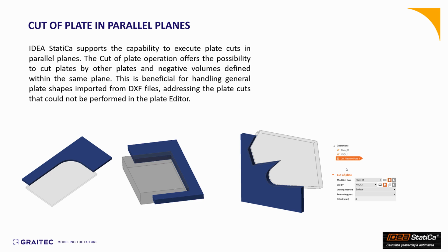Again, this is for cutting of plates. Before, you were able to cut the plates using the editor option or using the negative volume of members, but the problem there was that you were limited to some very simplistic specified sections. For example, you were not able to cut a plate using a DXF import. Now you have this option. You can actually cut a plate with a plate which is imported from a DXF.